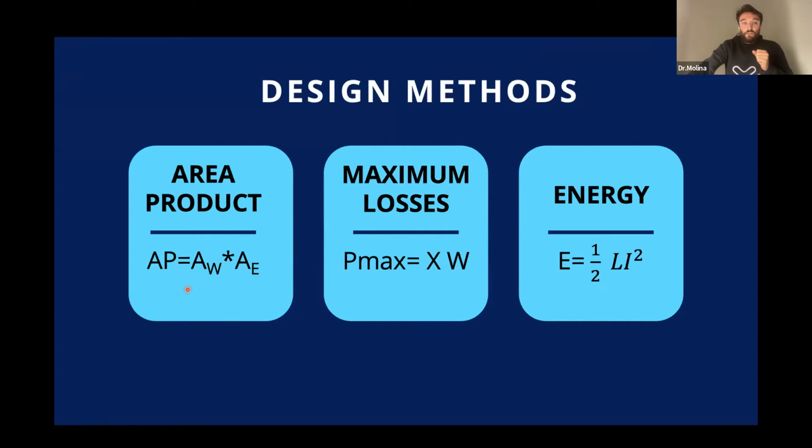And in this relation, once you have the value from your power converter, you go to the table and then you choose one that is a little bit greater than the value that you got from your converter, and this core will be the selected one, and then you can design the converter. I mean, you can design the magnetic starting from this core.